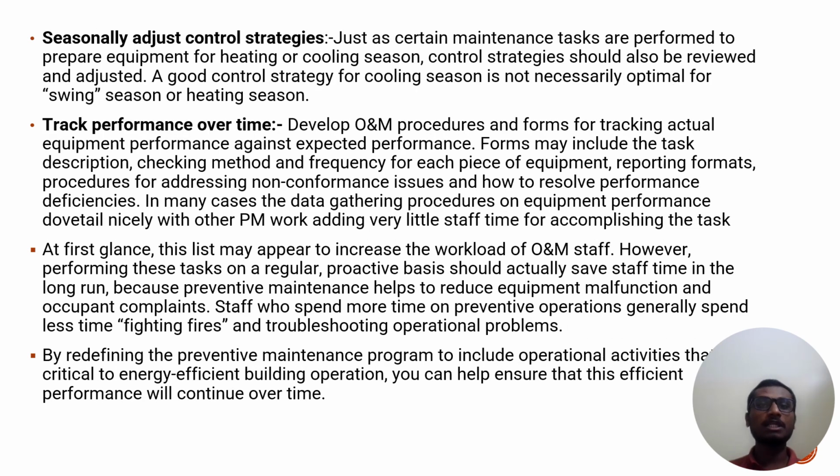Seasonal adjustments. Control strategies should be adjusted just as certain maintenance tasks are performed to prepare equipment for the heating or cooling season. Control strategies should also be reviewed and adjusted. A good control strategy for the cooling season is not necessarily optimal for the swing season or heating season.